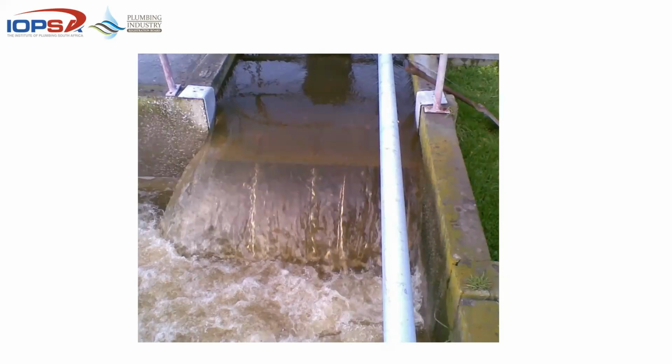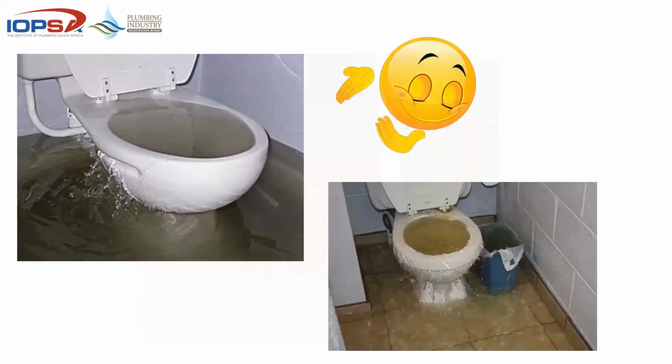And if you're not fortunate enough to have the system overflowing, or you don't have a proper system with a gully and an overflow, you'll see a lot of clean rainwater come through toilets and flood houses and flood basements, etc. Because if it can't get out the gully and it can't get out the manhole in the street, or you are below the street level, you'll find that the next lowest point, or the next entrance, would be an opening like a toilet, like a shower, etc. in the house, and we end up having damage in properties.